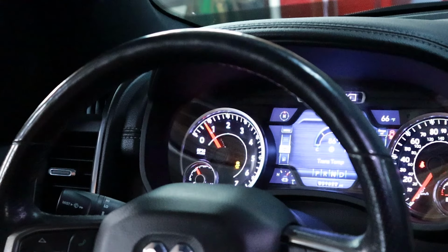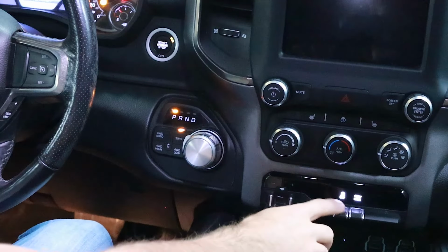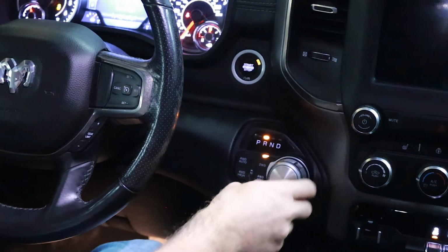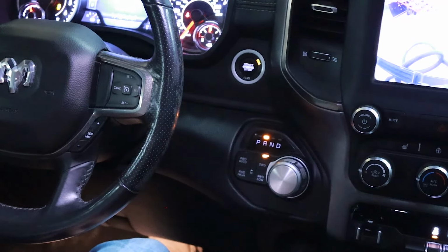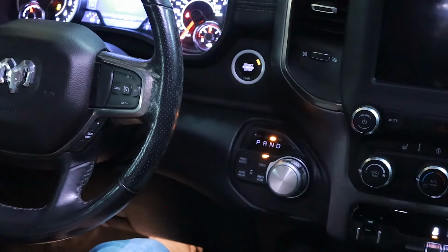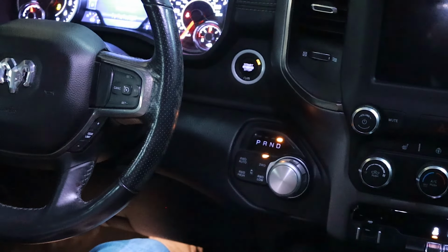At this point, the engine should still be idling with the vehicle elevated in a level position and the wheels must be off the ground. Next, disable the traction control using the dashboard button. With the brake pedal applied, shift the transmission into reverse for 5 seconds. With the brake pedal still applied, shift the transmission to neutral momentarily, then shift to drive for 5 seconds.